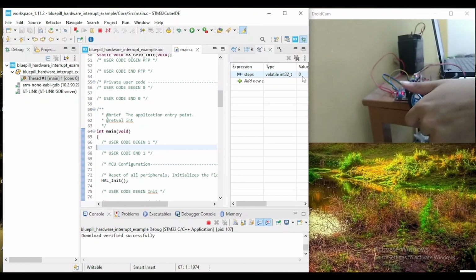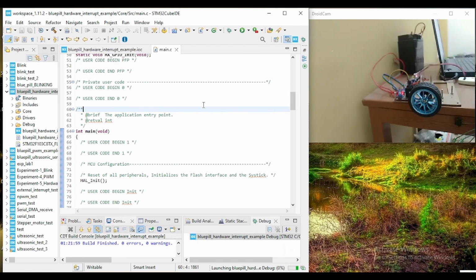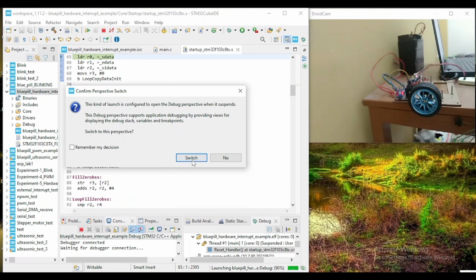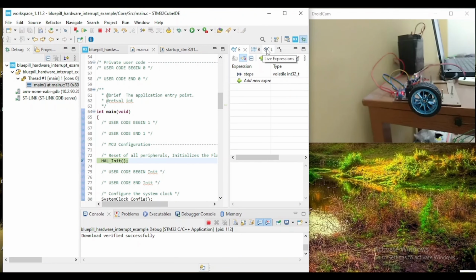We can see the tire being rotated by us. So when motors are involved, the code is often used to track movement, direction, speed for this motor to generate signals like pulses or waves to GPIO interrupt pins of a microcontroller. A rotary encoder is attached to the motor shaft, which has two output channels usually called A and B. These are square waves 90 degrees out of phase for quadrature signal. These signals are connected to GPIO pins, say PB10 or PB11.